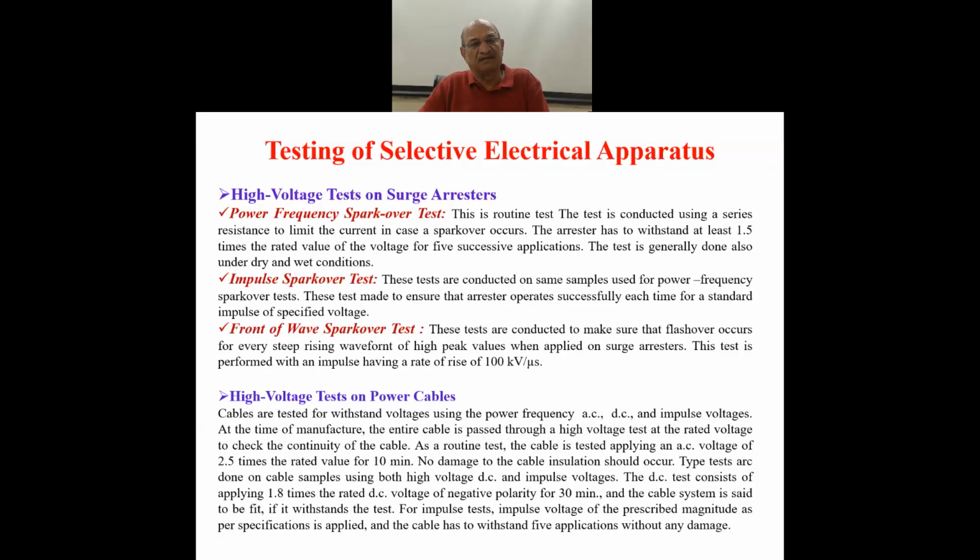The inductive reactance is adjusted automatically, either variable inductors are used or we vary the frequency, to make the inductive reactance and the capacitive reactance as close as possible, or under resonant conditions, when you supply only the real power.